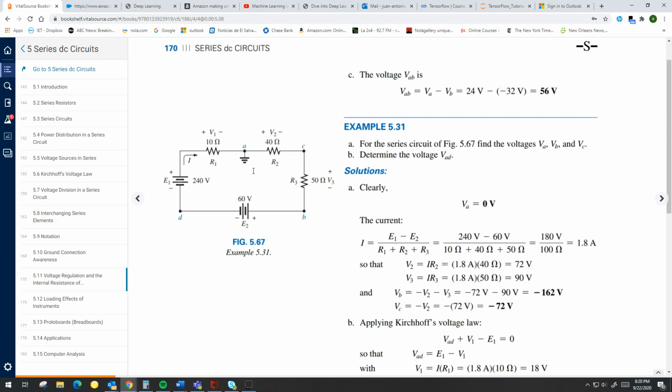So now it says find the voltages VA. So VA with respect to ground is just ground. This is the ground point, right? How will you measure that? Well, if you really need to do it, although it's obvious what the value is, you will put both leads at A, because you're measuring at A. So it'll give you 0 volts.